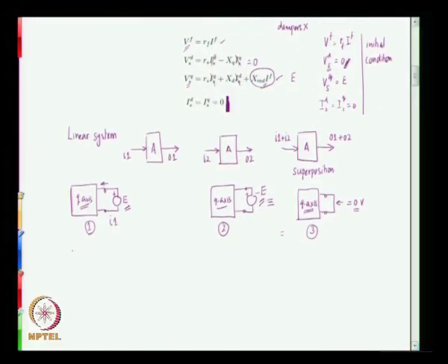So, therefore, there is no change in the field voltage as well, and therefore, the response to short circuit can be obtained as considering the response to q axis excitation as minus E. So, initially it was 0, and when you apply the voltage minus E, the sum total, which is 0 plus whatever is now going to come, is the short circuit current, and therefore, this response itself is the short circuit current.